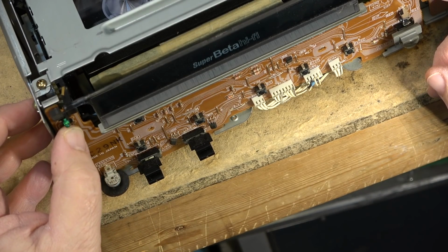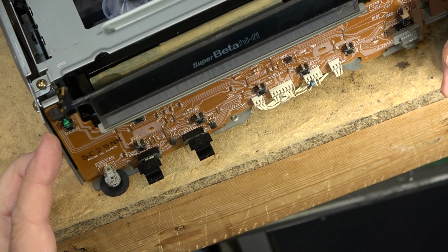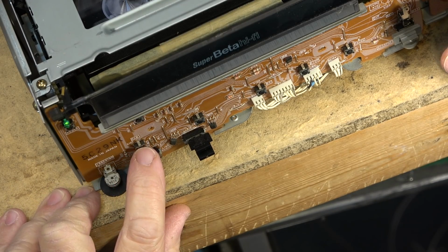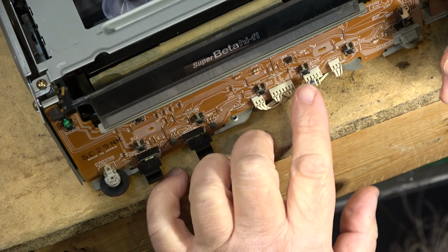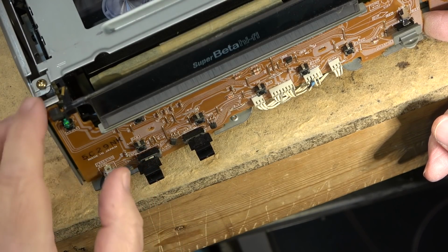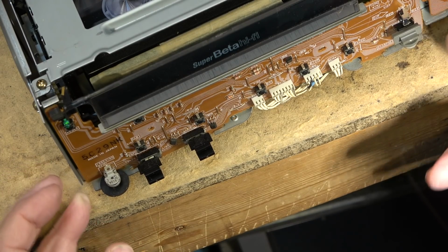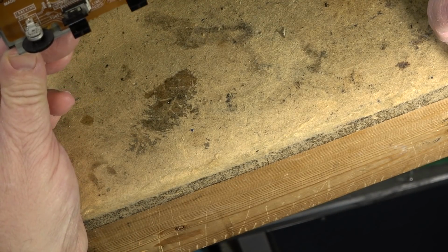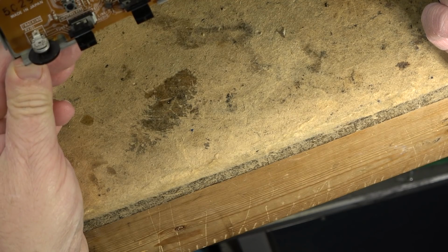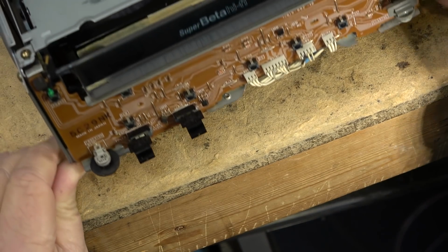But what's weird here is if we look at the power light, when I just move the board ever so slightly, the power light's kind of winking at me. I wonder if I press rewind now, does it go into rewind? It's still going into fast forward. That's strange. It's almost like the board may have a crack in it somewhere, which is totally possible. I think I got all the screws out of this unit. The board should lift out.